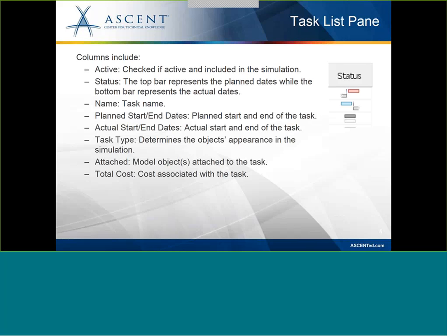You don't want your existing ground to show up through the entire process, because it might end up hiding some of the construction. Maybe you have to grade out that existing ground, do a lot of cut there. If you don't remove that existing ground during the simulation, then the building is going to be buried, and everyone will be like, are you on crack?